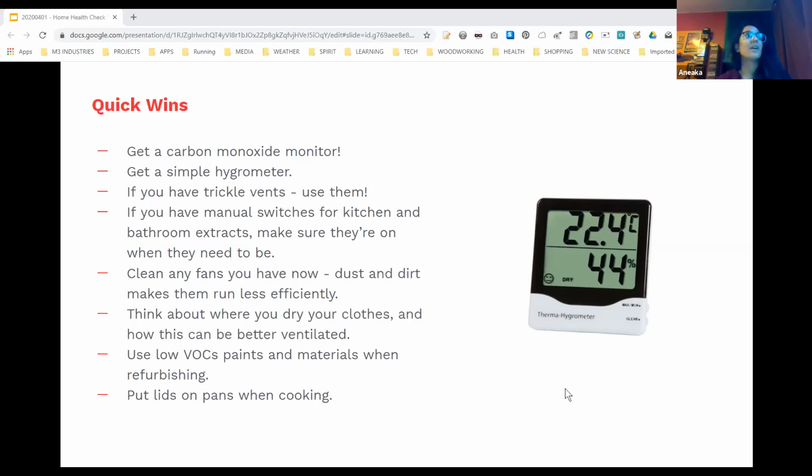In these flats, there's a balcony that goes out, built out of concrete, and it acts as a big thermal bridge, because the floor of the kitchen that goes out into the balcony is all one unit. If you imagine a cold bit of concrete out in the cold air, it's sucking lots of the heat out of the house, essentially. So again, that's a particularity of this flat, but flats often have balconies.